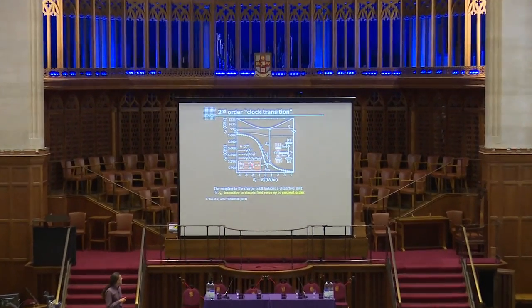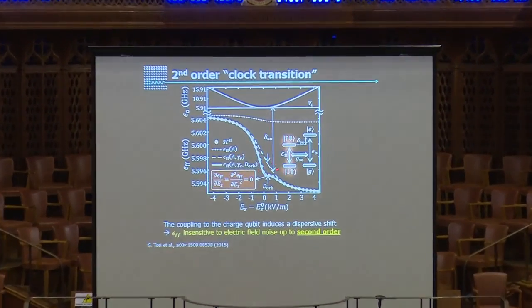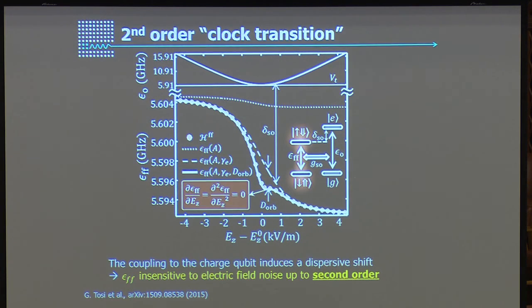Well, all that goes in there is the tunnel coupling. The way you calculate the tunnel coupling is with NEMO, with the full atomistic tight binding. Once you have the tunnel coupling, that just goes into a Hamiltonian that plugs in there.